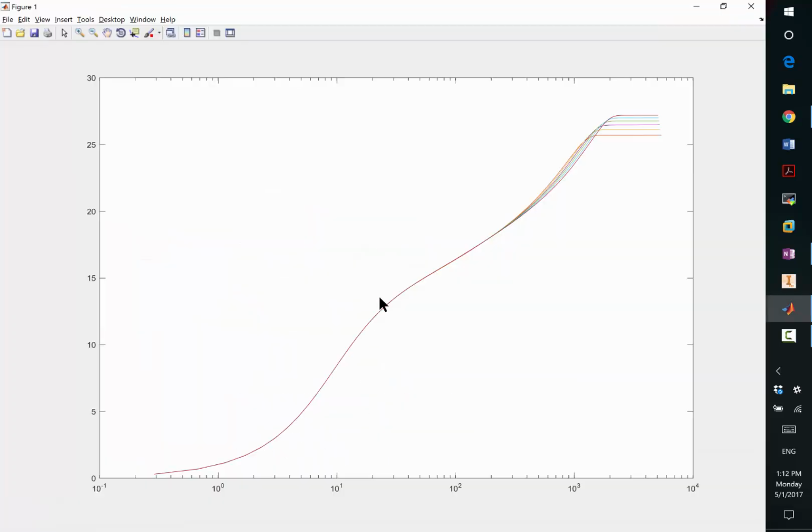So this is how it looks like. There are 6 different velocity profiles, but they all collapse on top of each other all the way to here. So this is what the inner layer looks like: the laminar sublayer, and the relatively straight log layer, plotted on a semi-log scale. If you have a straight line, that's a logarithmic law. All right. So this is the inner layer. Questions?